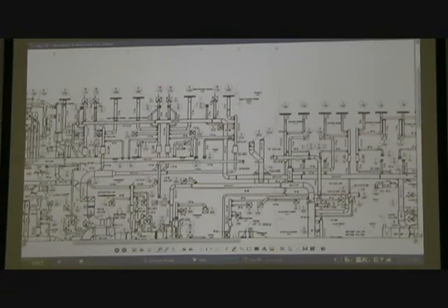This would be the high pressure duct right here. They've chosen to use square duct instead of round, so this duct would be the SMACNA duct. This is classified probably as 4 to 10 inches, and the gauge and reinforcement would be such that would stand that kind of pressure. They've shown some kind of odd fittings here that may or may not get built like that.